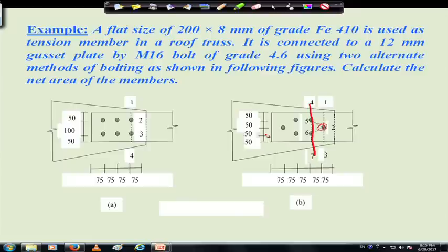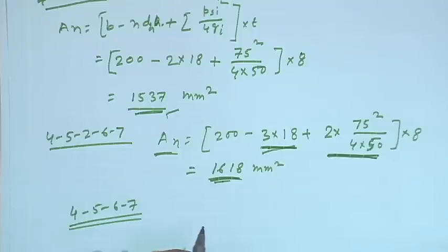The bolt 2 has to fail. That means, when we calculate the strength along this direction, we have to add strength of bolt 2. That means it will be more than the earlier cases. Therefore, we are not going to calculate this, because we know the strength will be more.